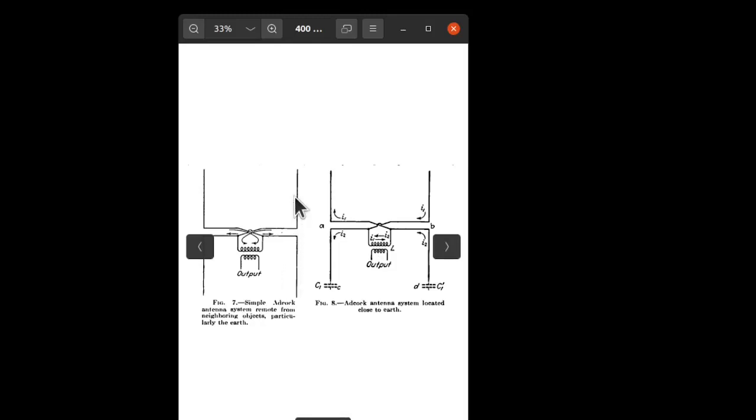What you see is this is quite obviously two vertical dipoles separated and fed with crossed transmission lines. That's what this element is all about here and here. These crossed transmission lines force phase relationships into the design that give us the characteristic sharp nulls that are so necessary for RDF.